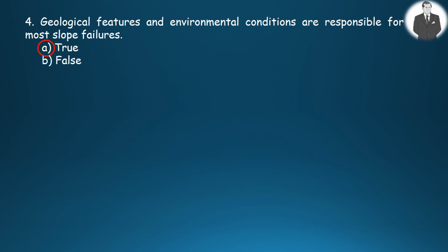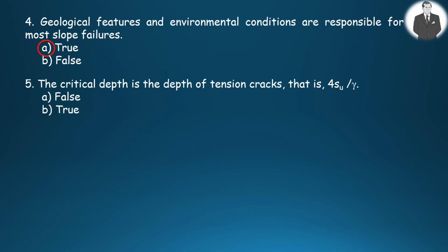Nice going. The fifth question: the critical depth is the depth of tension cracks, which is equal to 4 times S sub u divided by gamma. True or false? Yes, it is false. It is equal to 2 times S sub u divided by gamma.